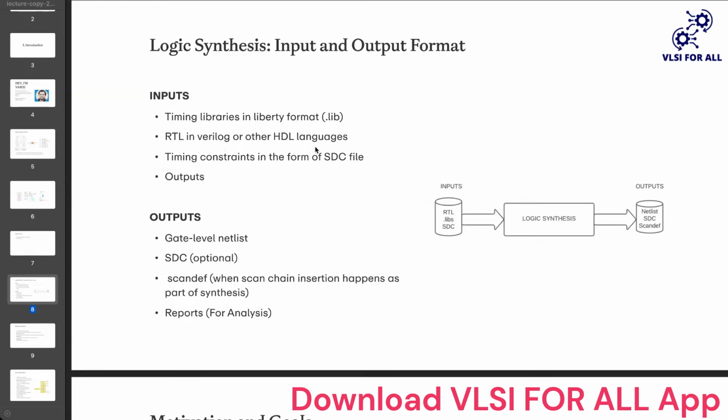Like I said, you have the VHDL code or the Verilog code, which is also an input for your logical synthesis. Timing constraints in the form of an SDC file. So what are timing constraints? Let's say I have a design. I can't just take the design blindly and convert that into gates however I want. There is a set of constraints to which that particular design is bound.